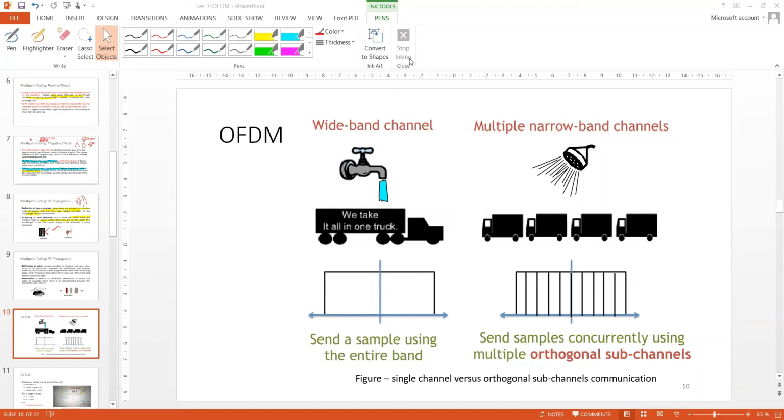Because of this, multiple copies of the signal can be received at the receiver, which can create problems by destructive interference. Multiple copies of a signal can interfere with one another, resulting in intersymbol interference, which can affect the quality of your communication, decrease the signal to noise ratio, and increase the bit error rates.